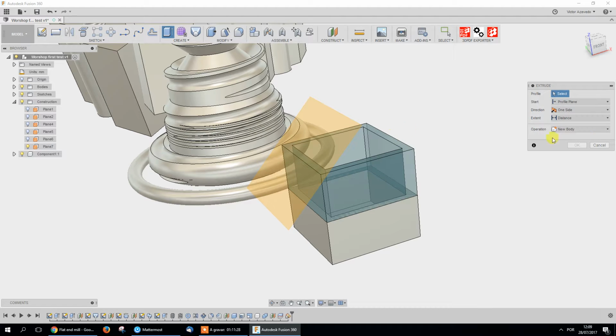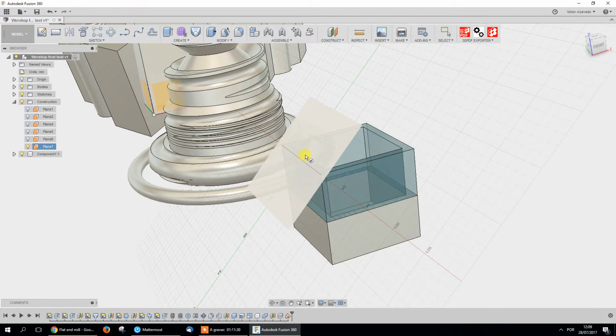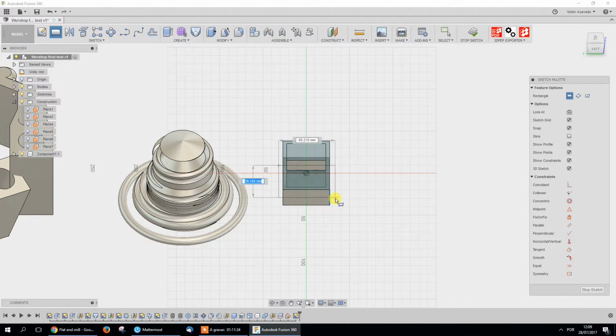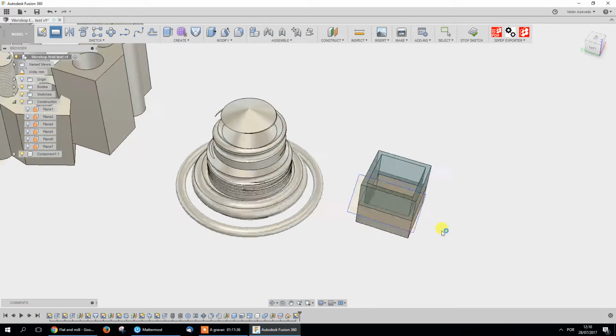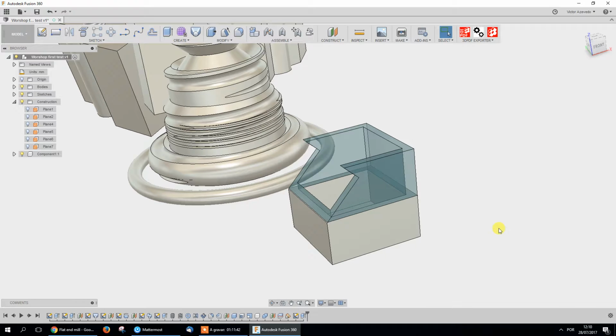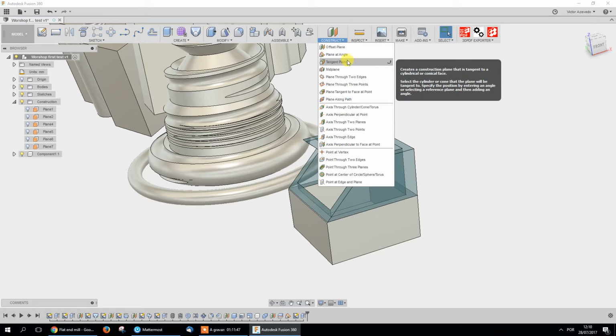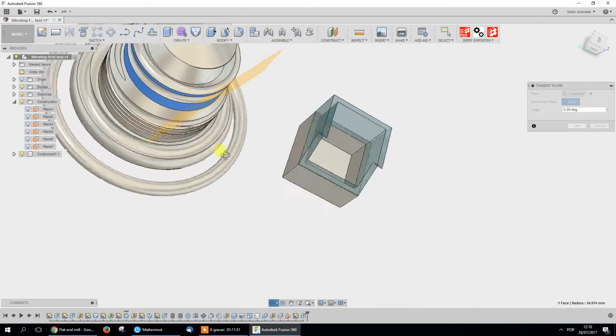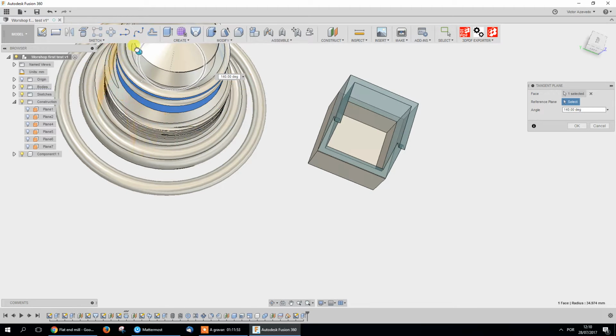Let's say I want to. I'll create a rectangle here. You have to be careful with the perspective again. Stop the sketch, extrude, and I can cut on an angle something. Okay. The same with a tangent plane. You need a circular surface, and then you just choose where you want the plane and start your sketch from there.